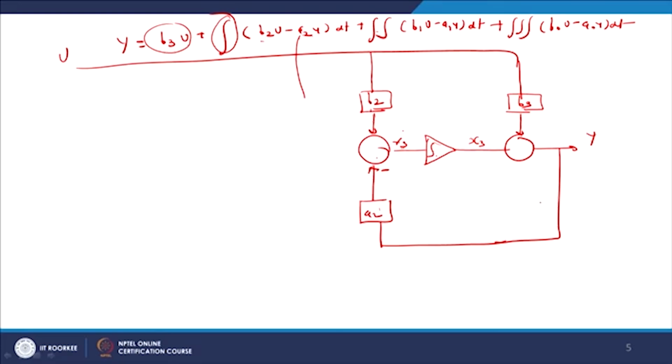Now, afterward there is another integrator. So, there is another integrator we have to write. So, here we show another integrator, these are 2 integrators. So, first and second, so another integrator we added. So, in this case we take another variable, here x2, and this integrator. So, now this double integrator output equals b1 into u minus a1 into y.